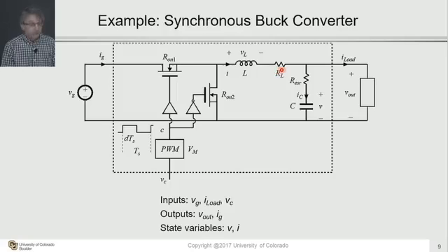We also take into account some series resistance for the inductor, and on the output filter capacitor, we take into account the fact that it's also not an ideal capacitor, but has some equivalent series resistance. Why is this called a synchronous buck converter?